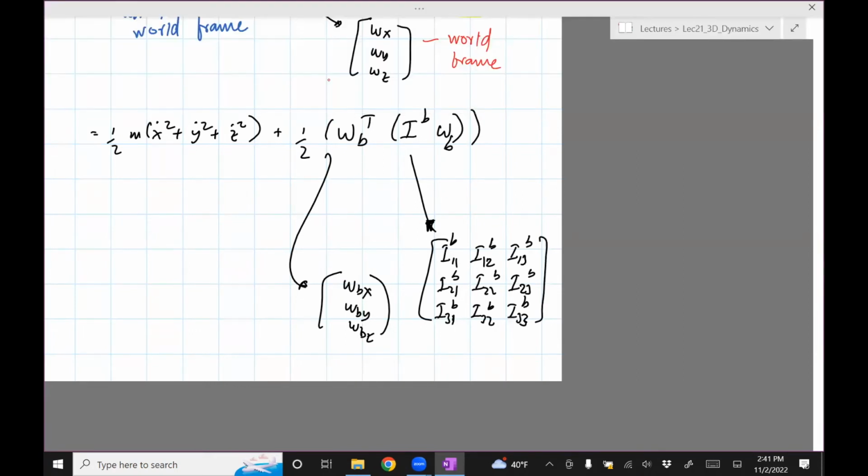So this is the inertia. I just put a generic inertia for a generic non-symmetric body, but many times if you use symmetric bodies, you'll see that this inertia boils down to this very simple form. Let's call that I1. That happens when the object is axisymmetric and isotropic, where the mass distribution is the same. The inertia boils down to a diagonal inertia for something which is symmetric.